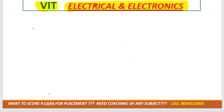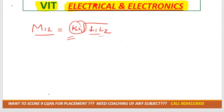As I told you, what is the formula for coefficient of coupling? M12 is equal to K12 into root of L1 L2. So M12 we know, L1 L2 we know, so we can calculate the value for the coefficient of coupling K12.